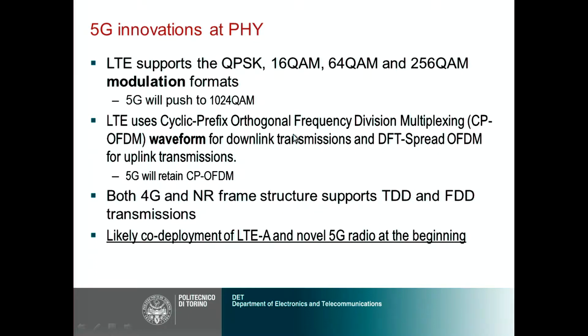Okay, this is just a detail. I have not mentioned this, but LTE uses two different ways of OFDM in uplink and downlink. In downlink, it's OFDM as I have explained it to you yesterday. In uplink, it's different. In uplink, it uses something called single carrier OFDMA.